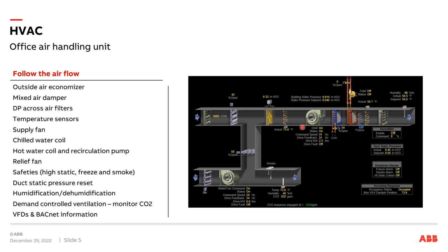So you can see there is some information that we can see on the graphics here. You can see it's on. It's being told to run at 31 hertz, and yep, that's what it's actually running at. The motor is drawing 2.2 kilowatts, and it is not faulted. So there's a little bit of data there. We can do better, which we'll talk about in a little bit.